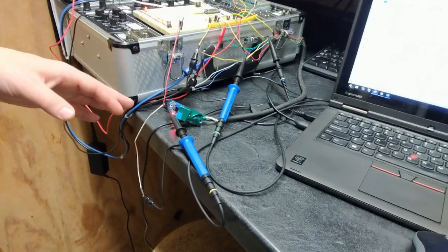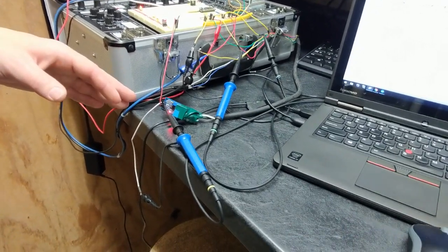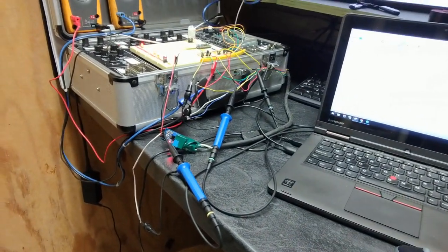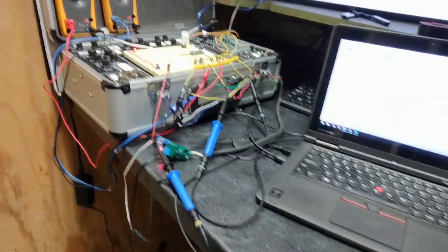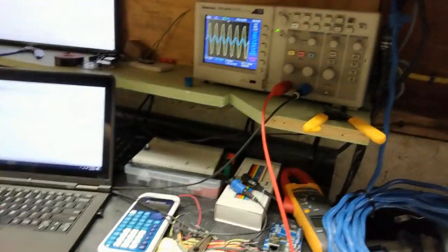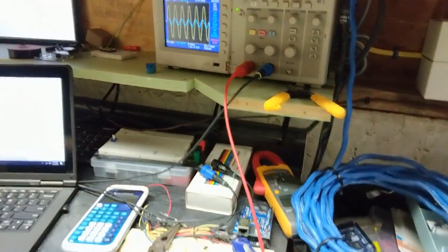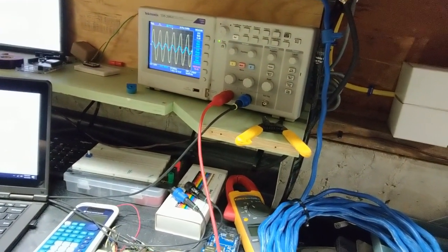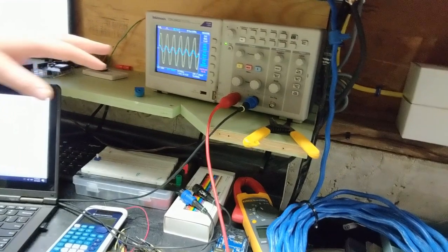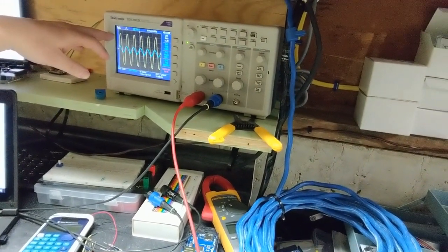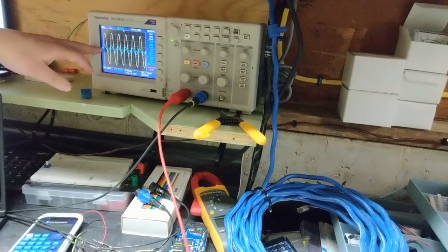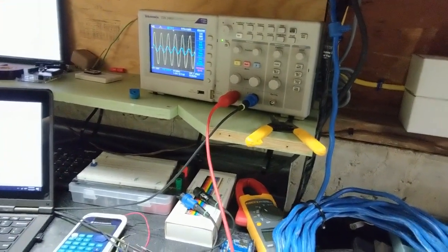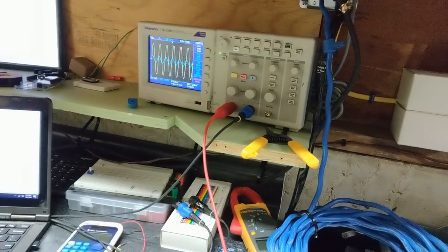The voltage collection was really difficult for us because we're using this device and we were having a hard time calculating our power factor. We couldn't figure out why. So finally, we were able to get it on an oscope so we could get the signal straight out of the wall into the oscope and compare the two. Our yellow is coming out of the wall, the blue is what's coming through our device, and you can see how the voltage angle between the two is pretty substantial.